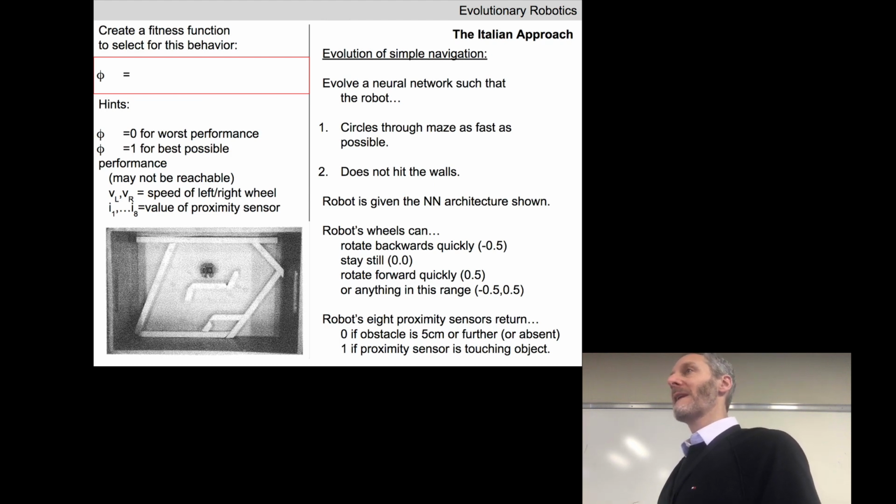Could use a weighted average of speed with the 0 and 1 proximities. Each step they're averaging in speed, it is 0 if, well, I think it's flipping it, but you count it if you're not bumping into something. Bumping into something, zero it out. Okay, if you're bumping into something, zero it out. So you said with, right? So how are we going to combine VL and VR? Let's imagine we define a new variable V, V equals VL plus VR. So we got one term there, V, which selects for velocity of the robot. How are we going to actually combine algebraically the i's into this?